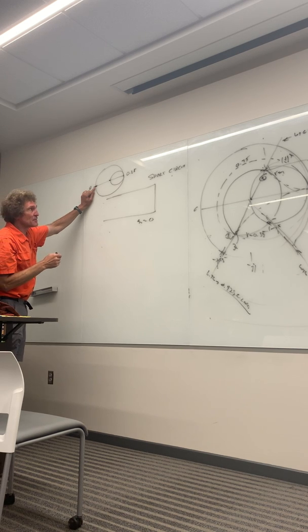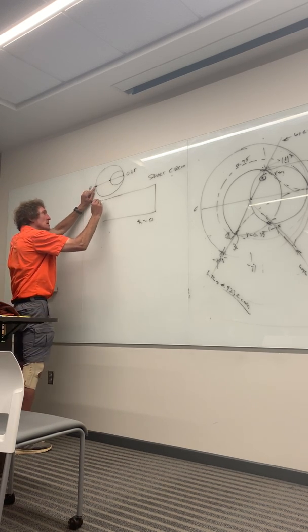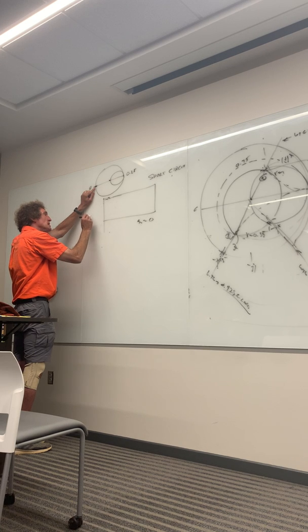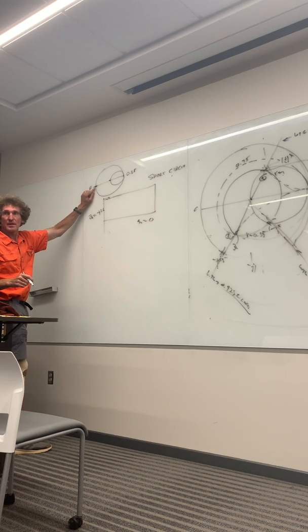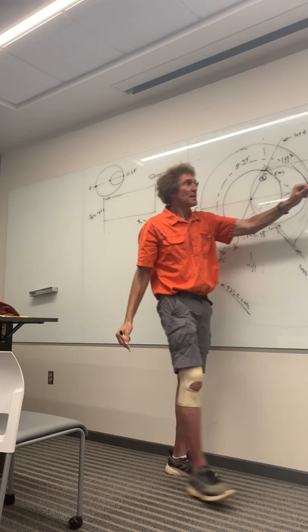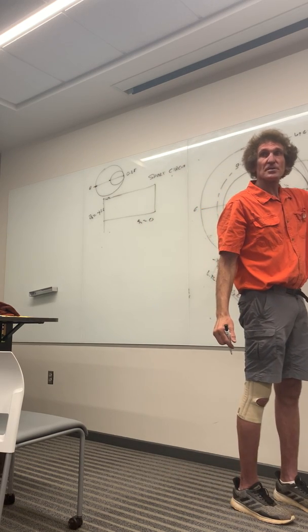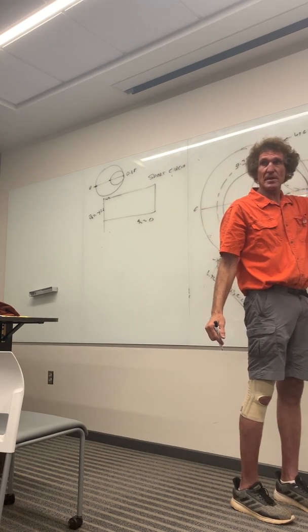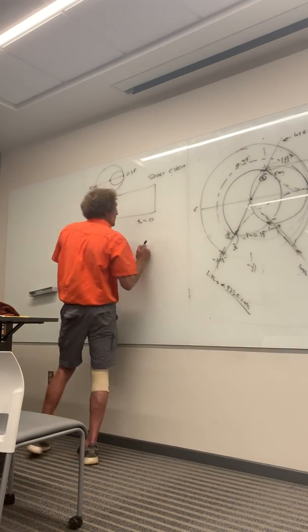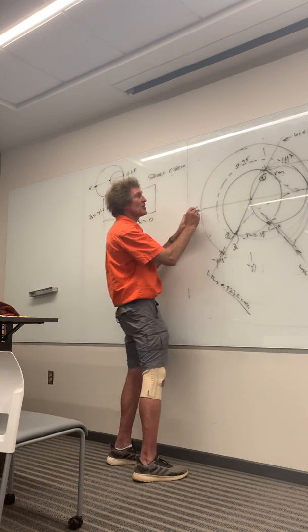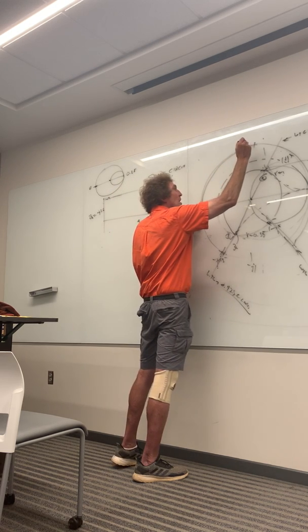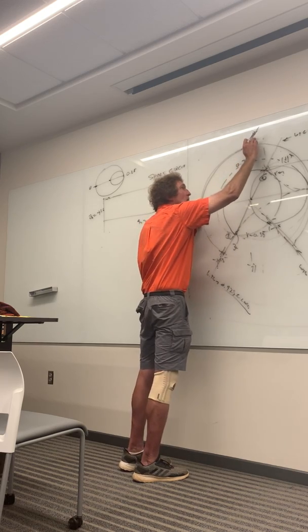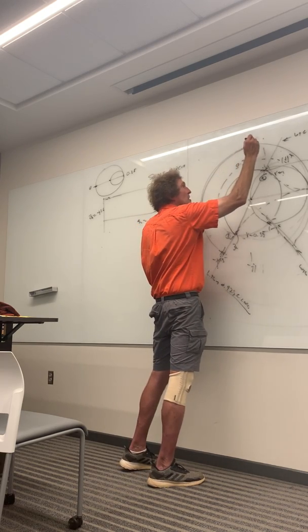Now, I want the value of Z in normalized to be equal to minus j1.6, correct? That's what I need, right? I'm replacing that capacitor with this transmission line, and I'm hooking it in series. Do you follow me? So what's that going to be? Well, I started at 0, right? How far do I have to move? I'm looking only at this outer rim. Well, right here it would be equal to what? j1.6, or j1 right here, right? Yeah, j1.